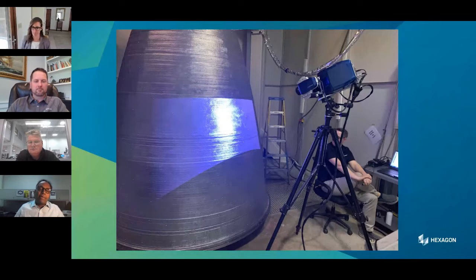If I have to adjust my datum because of the distortions to get a better fit or better machining. So to understand the machining strategy or to determine the final machining strategy, it is extremely important to do these measurements and then overlay the CAD and decide how to go about machining. Yeah, then absolutely, you need to do it again after finishing the machining process. Yeah, because it'd be so easy to scrap what could be a perfectly good part just for misunderstanding what exactly it is you have.